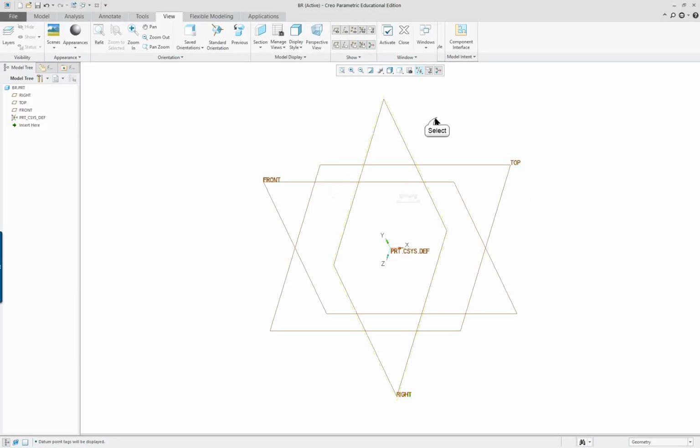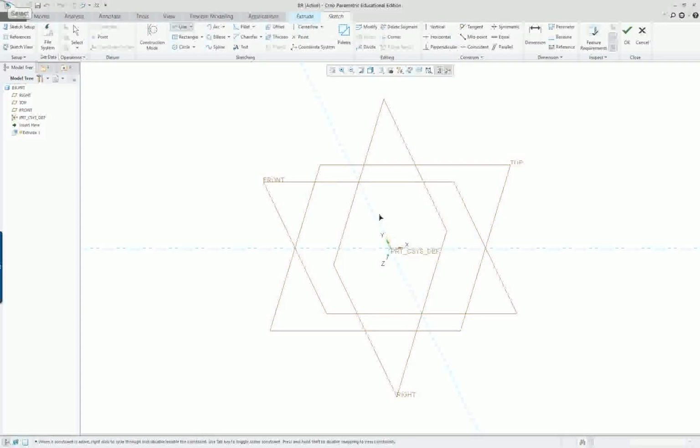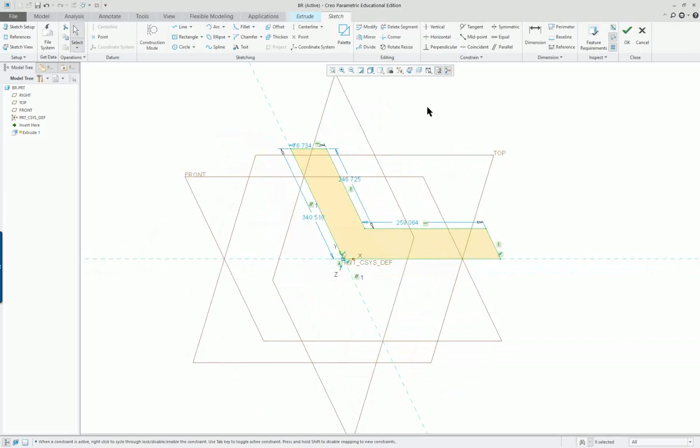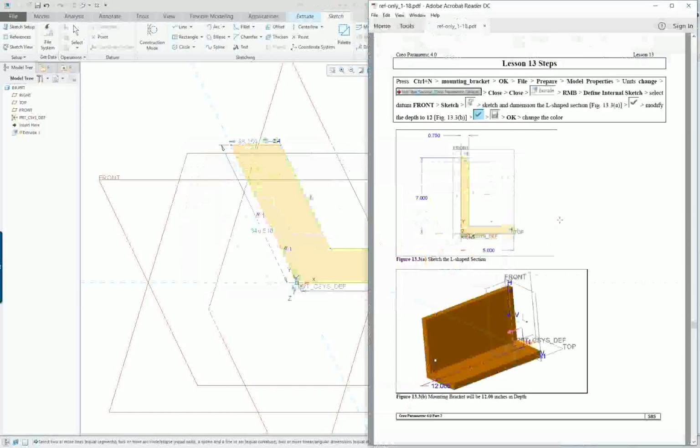All right, so we're going to just make a simple L shape, so it's an extrude, and click on line. I'm going to be careful with my constraints. There's my section. I'm going to make sure these things, it looks like they picked it up, but I'm going to click on equal because I want this line to definitely be equal with this line. No, they weren't equal, so now they are. And that's about all I need to do for the section.